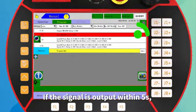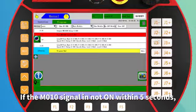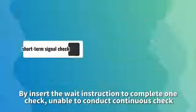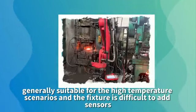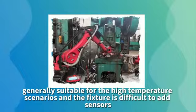If the signal is output within 5 seconds, the program will move on and the robot will run the linear motion command. If the MO10 signal is not on within 5 seconds, the robot will automatically give an alarm prompt. This is the short-term signal check: by inserting the wait instruction, we complete one check. It cannot conduct continuous checks, and is generally suitable for high temperature scenarios where the fixture is difficult to add sensors.